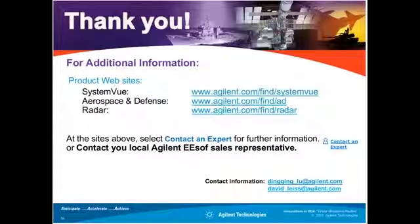Here's another question from Francis. For Ding-Ching, can we design a multi-static radar system using SystemView? Yes, we can do it. Right now, although we don't have exactly a multi-static radar example here, all the components are there. We just need to put them together. For example, you can create a transmitter using the existing radar transmitter plus the antenna model, then point the beam in some direction.